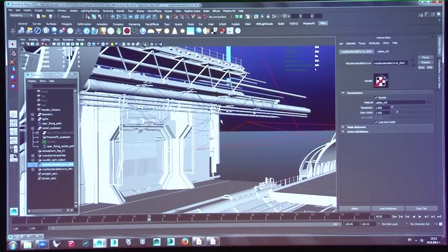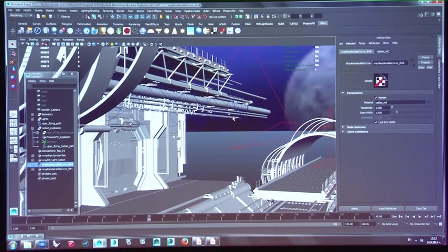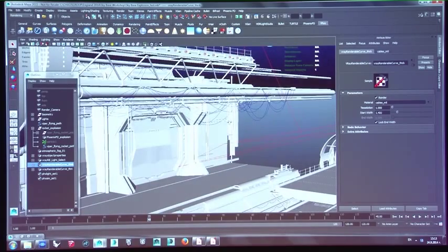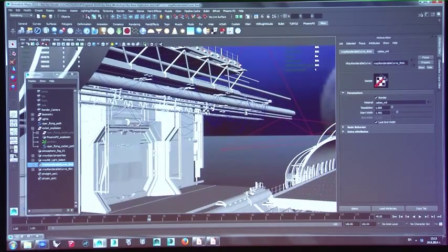The important thing here is that my viewport is not being cluttered with the additional geometry, and I'm also keeping the flexibility that if I want to change the shape of the curve, it is going to be done at render time by V-Ray, and you will not see it in the viewport. So no cluttering, and you don't have to re-extrude it every time you want to change the shape or the width or whatever. And it doesn't waste any computer resources.